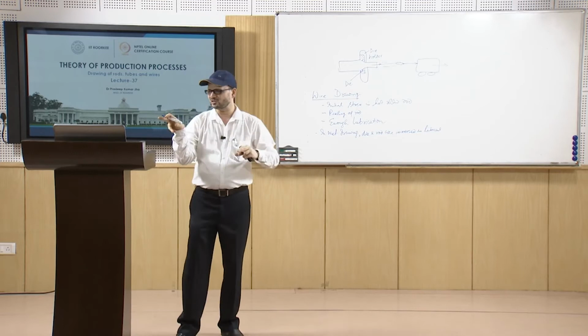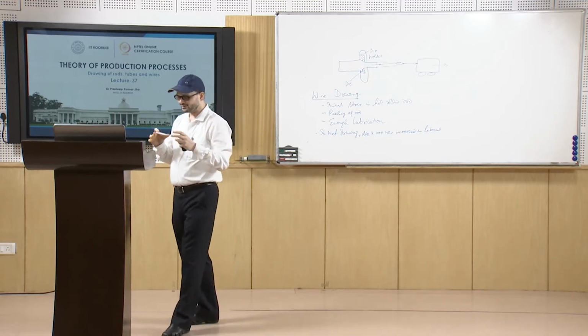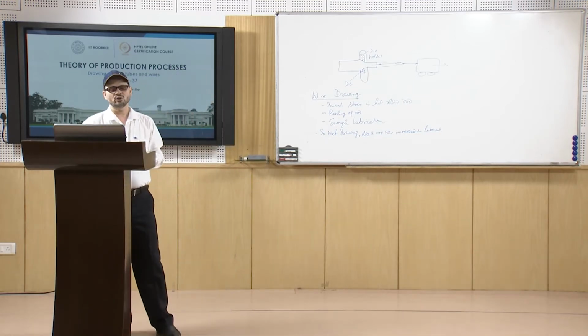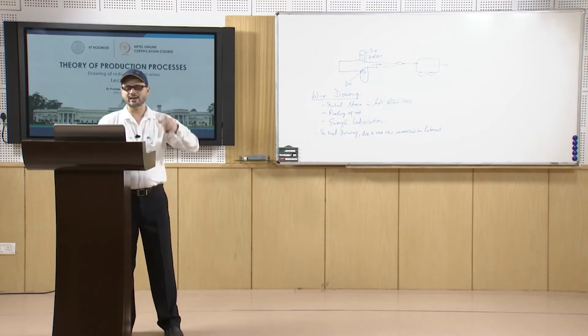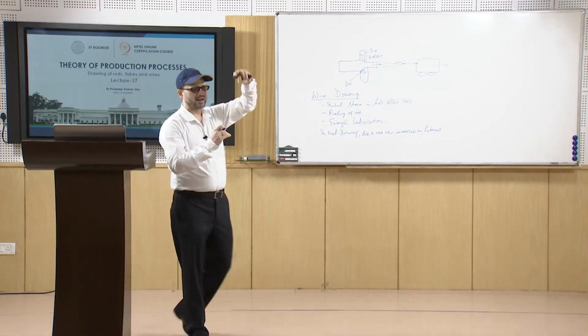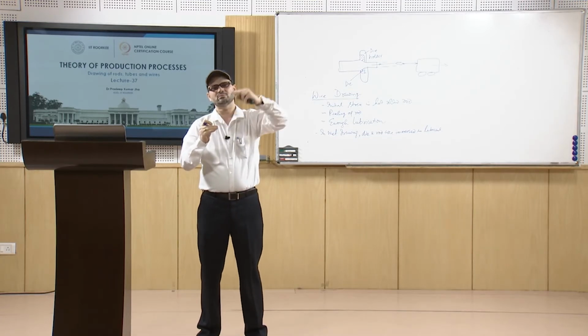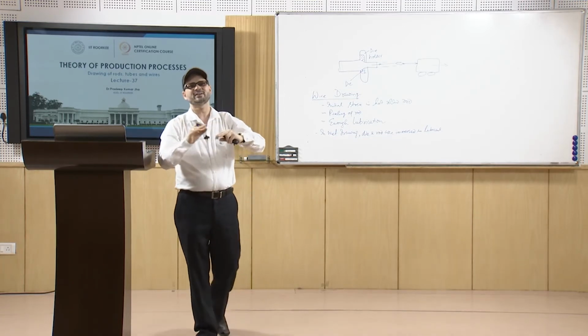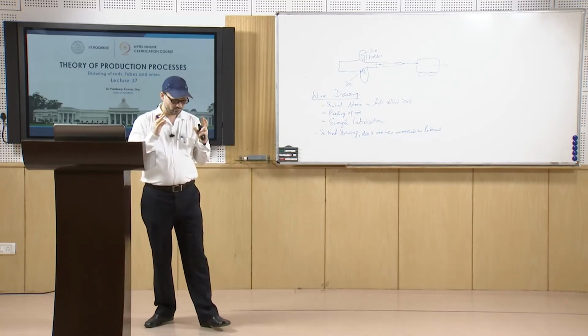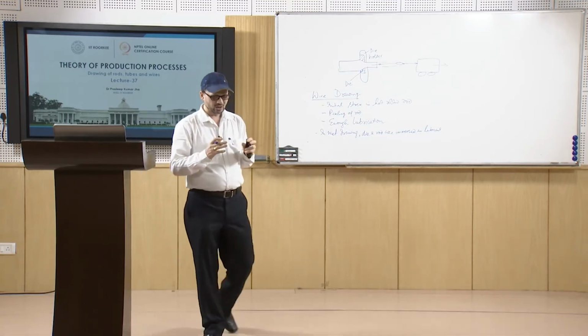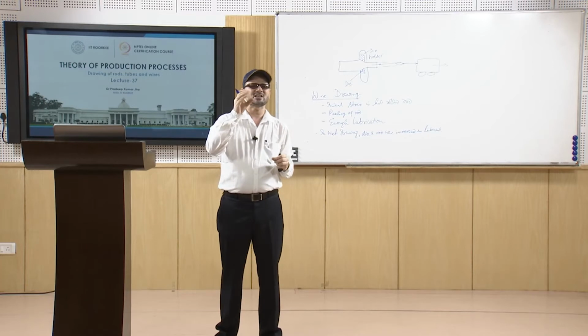For the steel wires, basically you go to a high temperature, and then from the higher temperature you come to a bath which is maintained at 315 degrees C. Finally, the purpose is to yield the fine pearlitic structure.